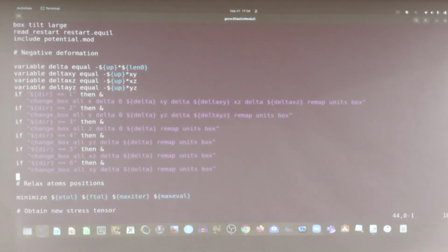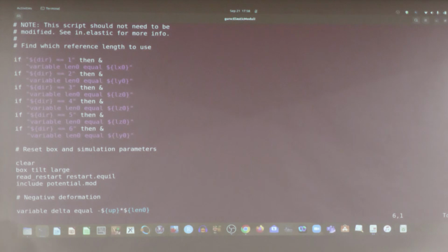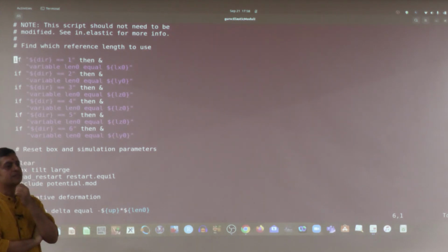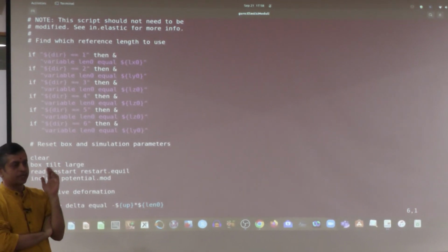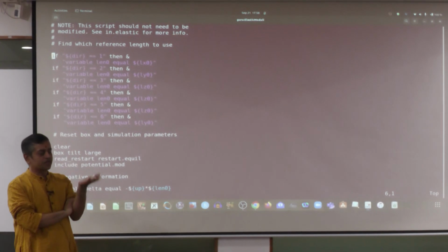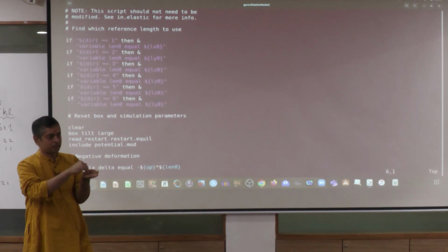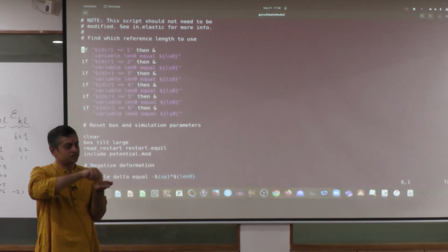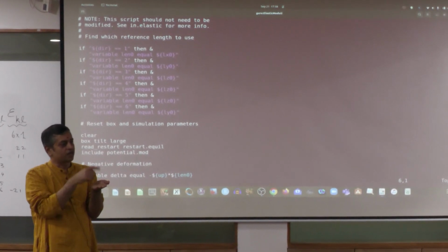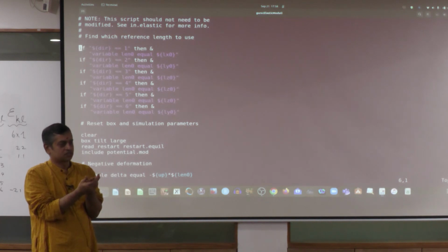So, what did he do? What is being done? Okay. So, basically to get the modulus, we are still going to get the region near the minima, and we are going to map out the energies by making small deviations from that minimum position, and we are going to fit that data to a parabola, and the curvature is going to give me the modulus.